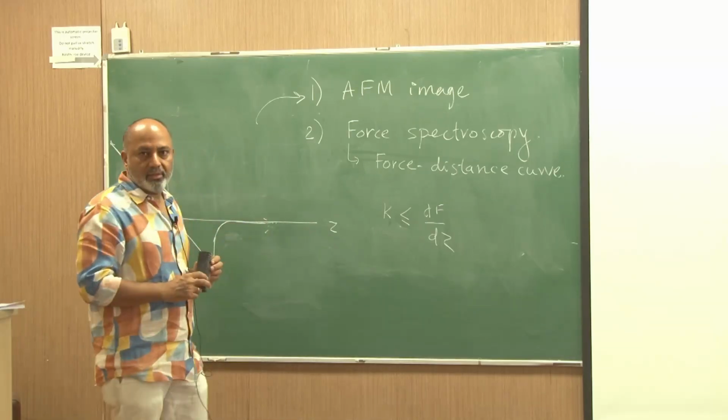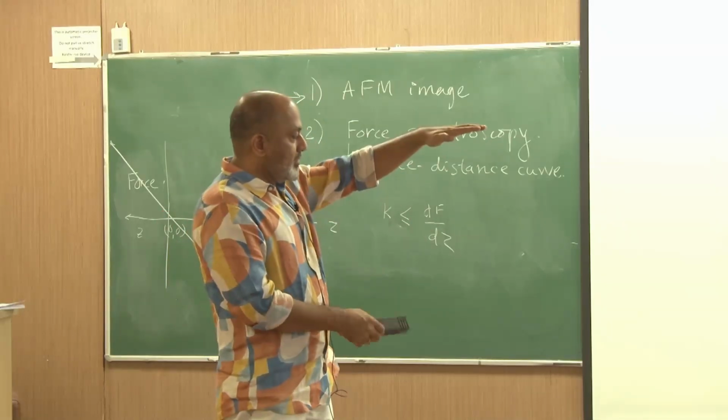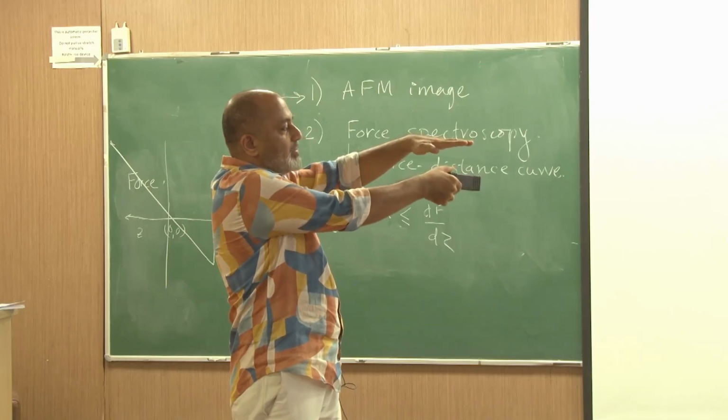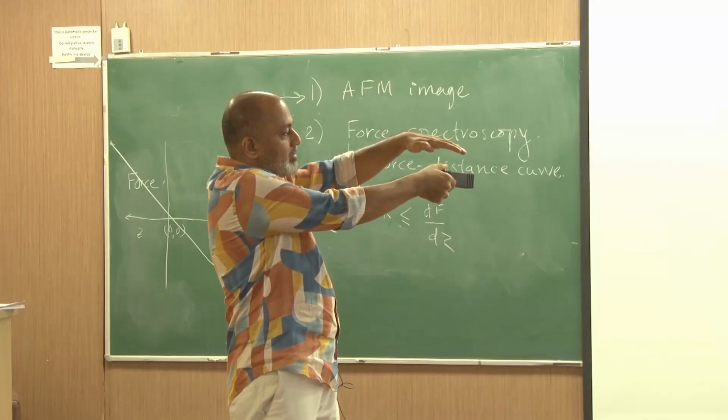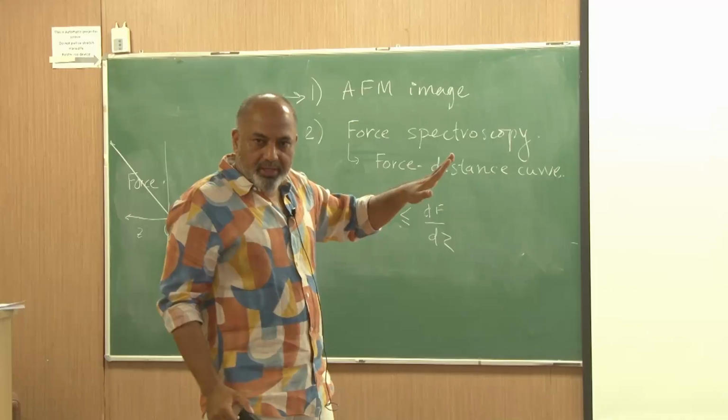But in typical contact mode imaging using AFM, what you do is you basically approach, and if the cantilever is stiff, it does not bend too much, while weak cantilevers bend a little bit, and you hit it, and you are loading the cantilever in a backward direction.